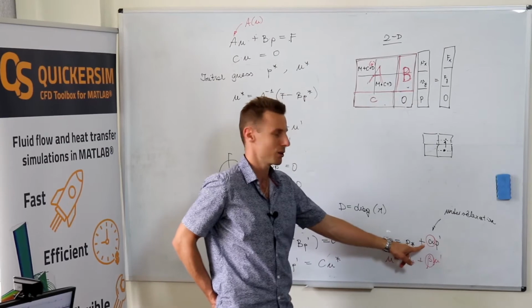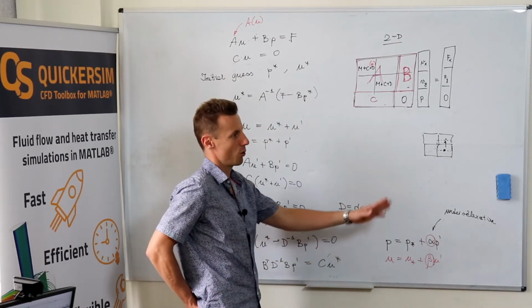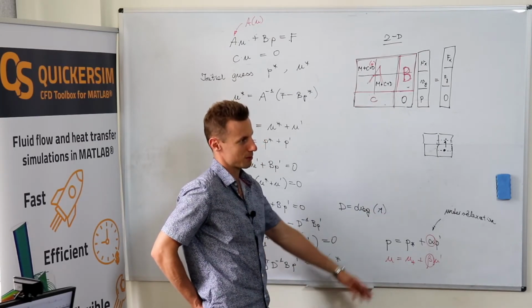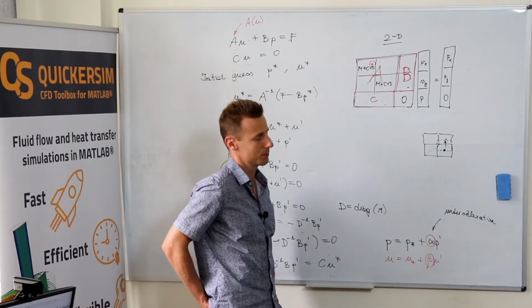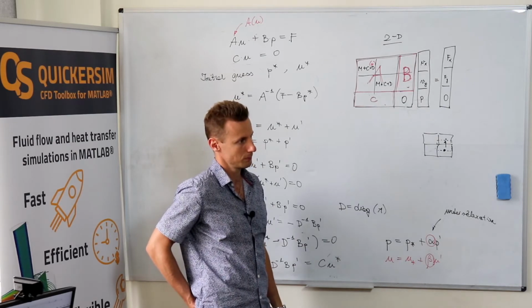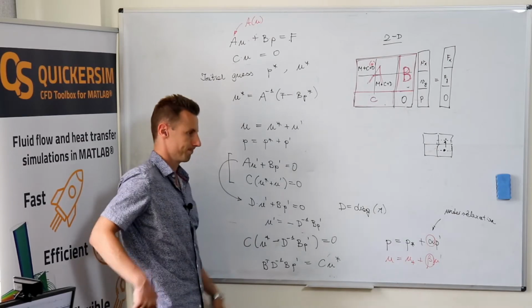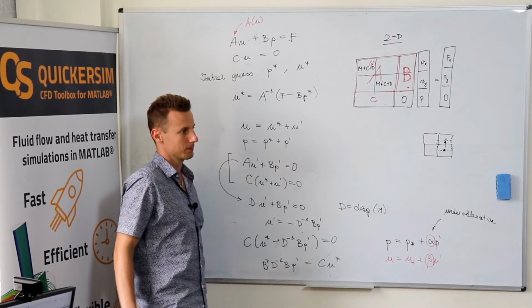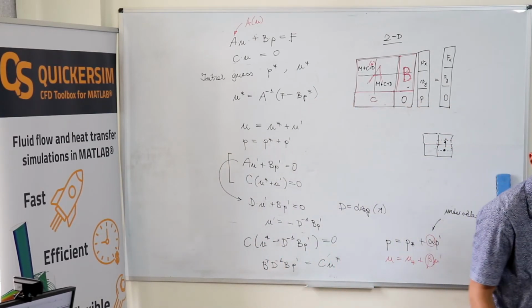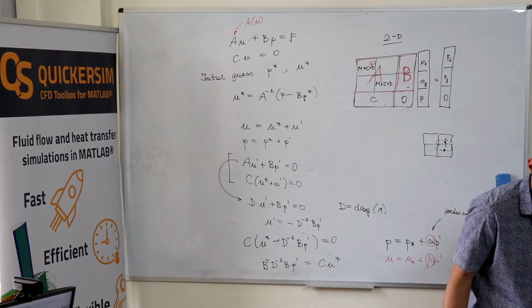So this might also be that ANSYS Fluent somehow uses its own definition of the under relaxation parameters multiplied by something. I don't know. Maybe it uses it during the computation of the corrections. I was expecting it to just become evident in this analysis you were doing, and I just don't see it.